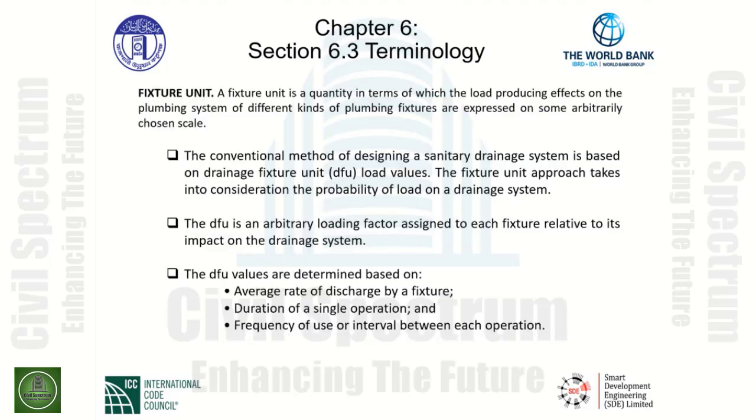Fixture unit. A fixture unit is a quantity in terms of which the load-producing effects on the plumbing system of different kinds of plumbing fixtures are expressed on some arbitrarily chosen scale. That arbitrarily chosen scale, however, is somewhat well-defined based upon probability.